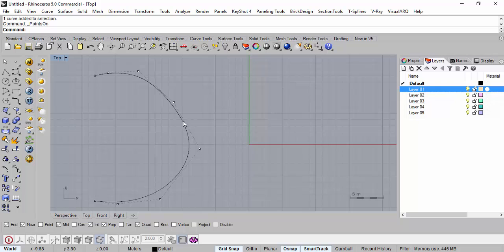For example, you have a JPEG image and you have a curve drawn on the JPEG image. You'll be able to use this method because then you will click on the point on the image, and precisely the curve will go through. Whereas the first option won't be the right option, because if you click on the lines of the JPEG, it will put the control points there and not put the curves there. Whereas this one will put the curve, the line, exactly on those points. Only thing, your control points will still be detached. I mean, they won't be along the curve. So don't confuse that: because the curve passes through the points, it doesn't mean the control points are embedded in that curve.